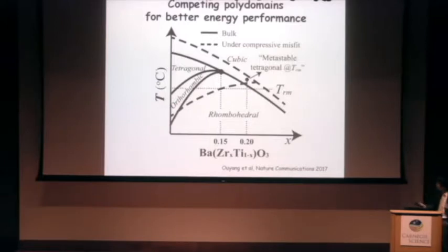So I tried to make it rhombohedral, to allow the polarization to have a certain angle with the applied field. In this case, I doped it with a little bit of a larger ion, zirconium. It's larger than titanium. So you drag the stable phase from tetragonal to orthorhombic until you go to the rhombohedral. Until you hit 25% or higher, you get a relaxor. I don't want to go to that side. So I picked something at 20%. We know it's rhombohedral in the bulk.